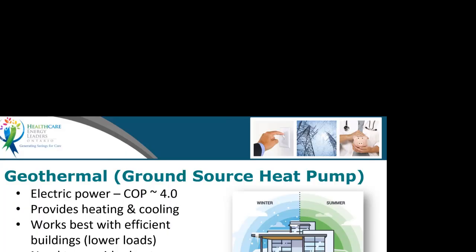But we can maintain a relatively high, what we call refrigeration coefficient of performance, maybe 4 or above. So that means for every unit of electricity we purchase, we can deliver 4 units of heat from one of these heat pumping systems. That's pretty good, because that takes the cost of electricity now and all the other things attached to electricity like carbon and cuts it by a factor of 4, right? So that's the benefit.